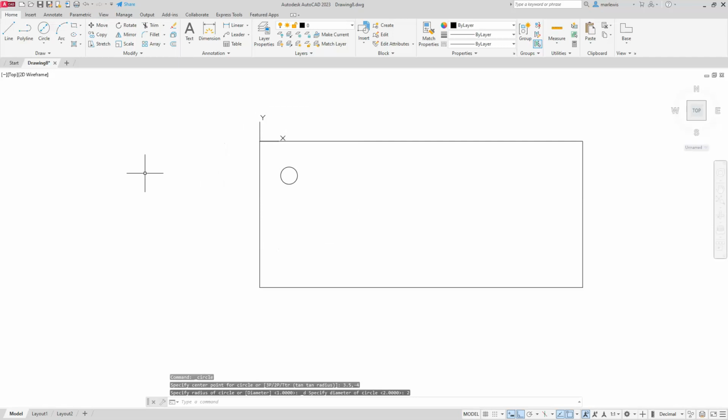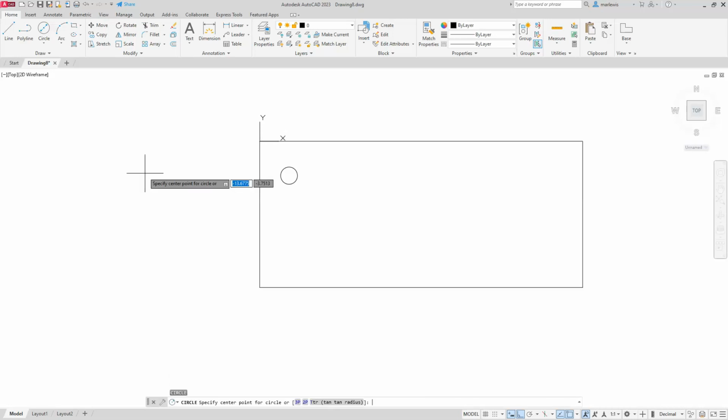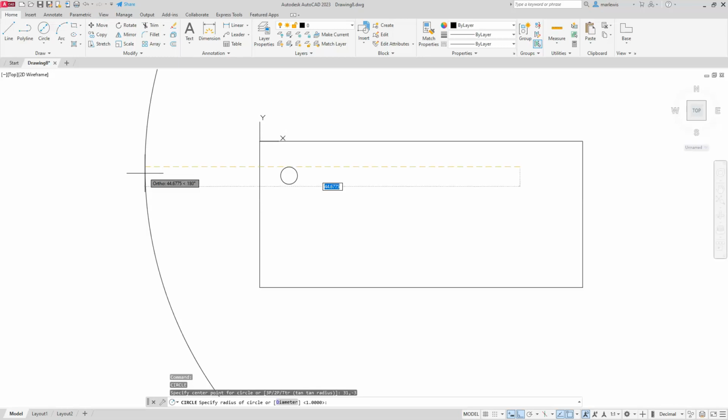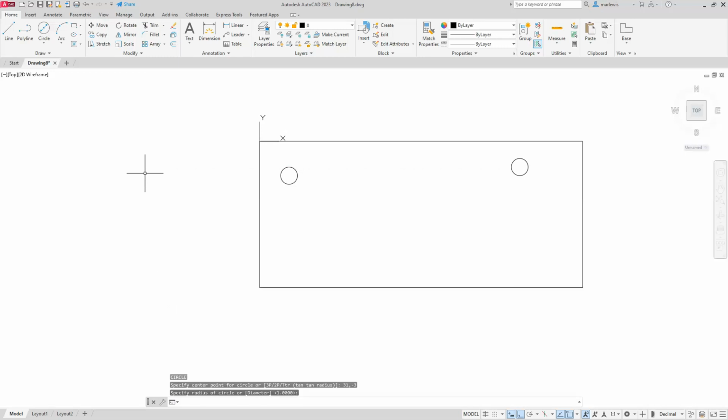Okay, so next let me go ahead and type in my next coordinates. You can remove your hand from the mouse altogether because you won't need it for this next step. I'm just going to hit the enter button. You'll see that it takes me back to the last command, and then I'm going to type in that distance which I calculated earlier, which was 31, comma, and we're still going down, so that's going to be a -3. Enter, and that should place it in the right location. Don't worry about the circle being big or off your screen. Just hit the enter button one more time, since it does remember the last diameter that it needs.